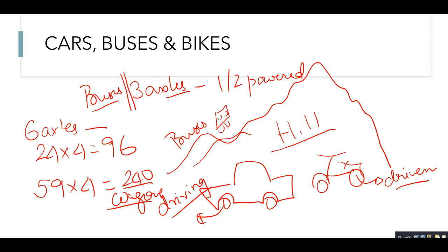That means that you really can't navigate this kind of sharp gradient, and that's why even the working timetable is so specific about mentioning the ruling gradient. Even a gradient of 1 in 200 or 1 in 300 becomes a big thing for a locomotive. I'm sorry, not 1 in 200 or 1 in 300, but something like 1 in 50 becomes a great deal for a locomotive, but it might be something that a car or a bus can quite easily negotiate.